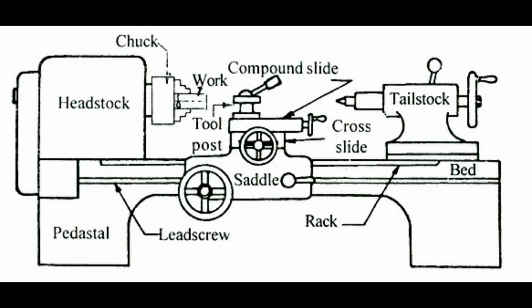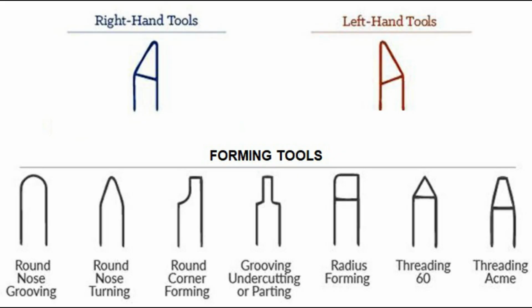There are several types of lathe tools, from knurling wheels to boring bars. The most common type of lathe tool is the knife tool. This can be either left hand or right hand. There are also forming tools for making grooves and radii, and 45-degree tools for making chamfers. There are also specialist tools for screw cutting threads.